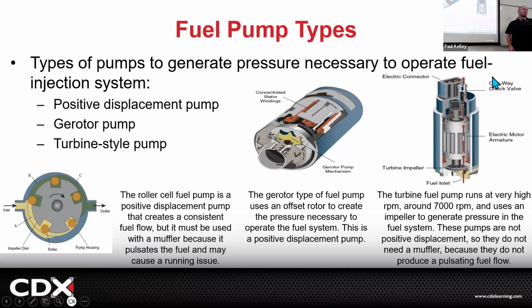Normally, it's not that complicated. It doesn't work. You know that the motor is bad because it gets 12 volts and ground. That's it. Once in a great while, it could be a complicated one, like that one. But wait, there's more. What if your motor is healthy, but you've got wear on this gear rotor, or if it's some kind of a sliding vane type of pump?